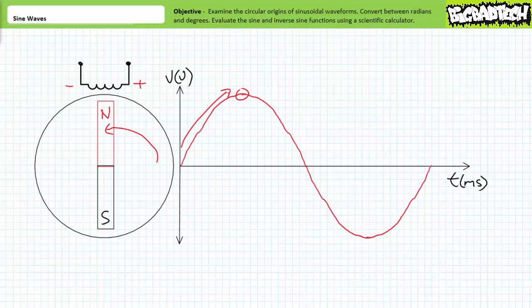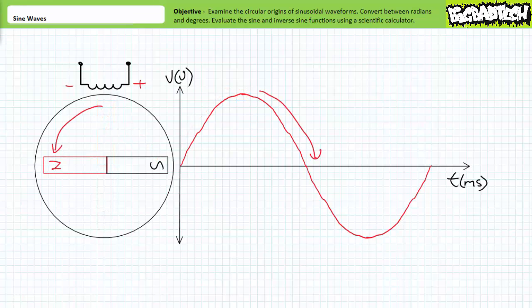However, as the rotor is driven counterclockwise, the north pole gets closer and closer to the stator, and induced voltage peaks out at 90 degrees. As the rotor continues to drive counterclockwise, the north pole gets further away. The induced voltage during this quarter is still positive, but decreasing. At 180 degrees, the north and south poles are again equidistant, and induced voltage is 0 volts.